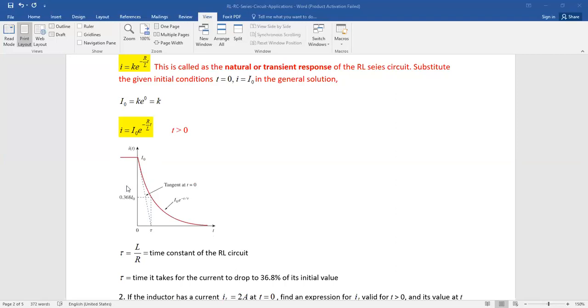the response is exponential decay. You could see the value of the I decays as the t increases. Okay, so in that case, since it's decreasing over time, we expect that if the problem is saying what would be the current after a very long time, so take note, that would be similar to asking what would be the current when time approaches infinity. After a very long time is t approaching infinity.